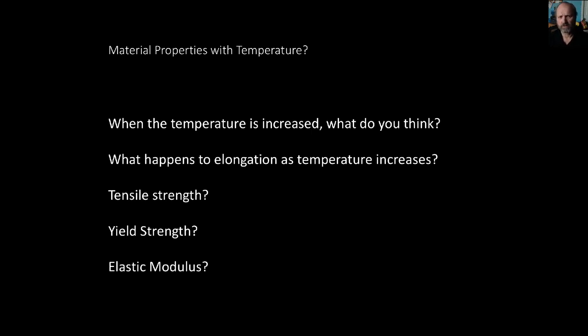So, if you think about it and go back to the case of taffy, right? We played with taffy before. It's kind of a fun material. If you warm it up, it's easier to pull, right? So oftentimes when they make taffy, you see it's warmed up. They pull the taffy and they create all the different candies out of it. So you can also do the analogy that if you heat up metal, it gets easier to pull on. It stretches easier. We call that ductility. So the ductility actually increases, right? We can elongate the material a lot easier for the same forces.